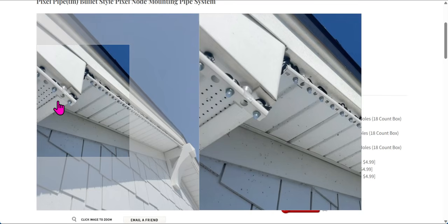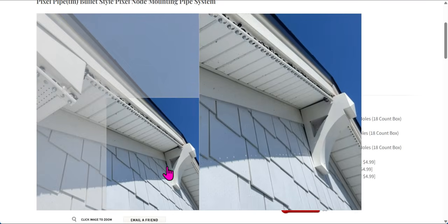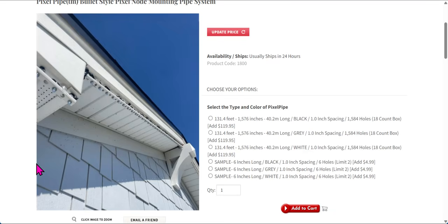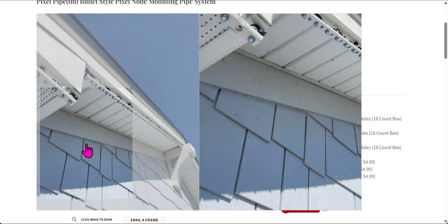Now, if you are doing a permanent installation, you do need to consider a few extra things. First is controller location. In a permanent installation, we will typically mount controllers into attics or concealed spaces because these need to be around all year round, and we don't want them out and exposed where possible, and also for aesthetic reasons. So consider where you're going to be running your cables. Also, that controller needs to be accessible in the sense that it needs to be able to have its playback sequences updated.